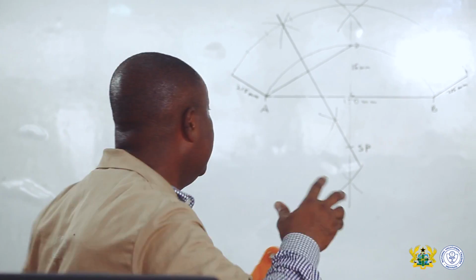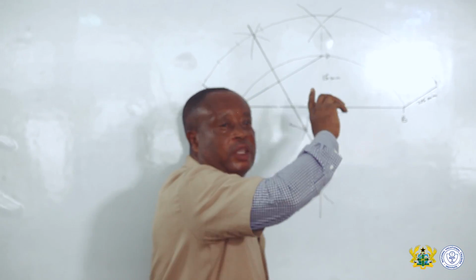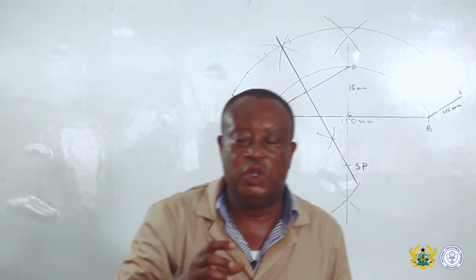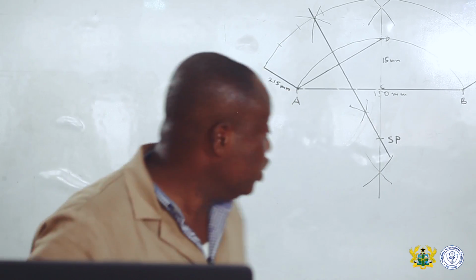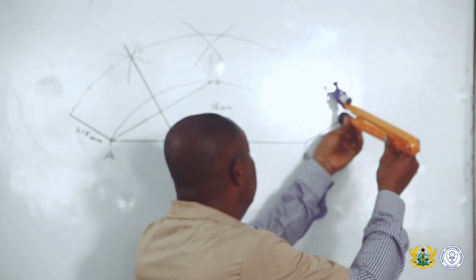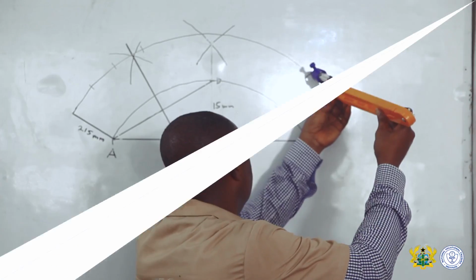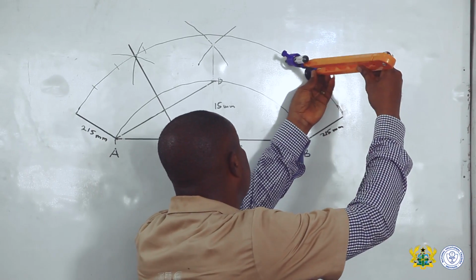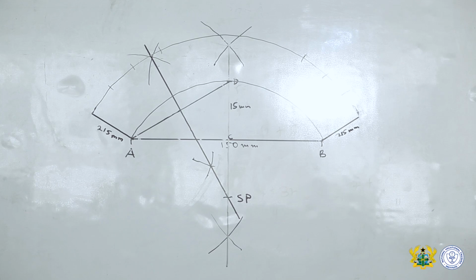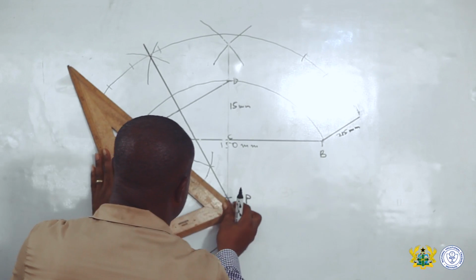The reason is that the last one is always the one to be placed, and this one goes to lock our arch for us. So with the same dimension, we can now step on the other side and mark the thickness of our voussoirs.